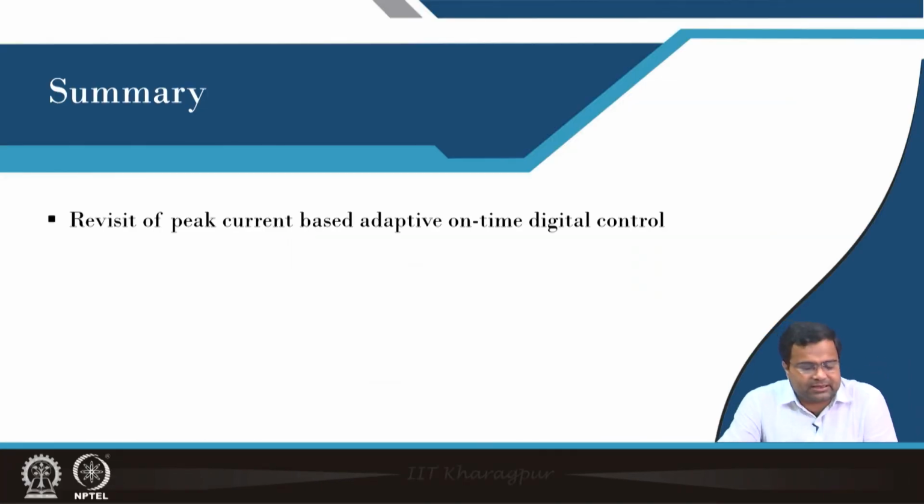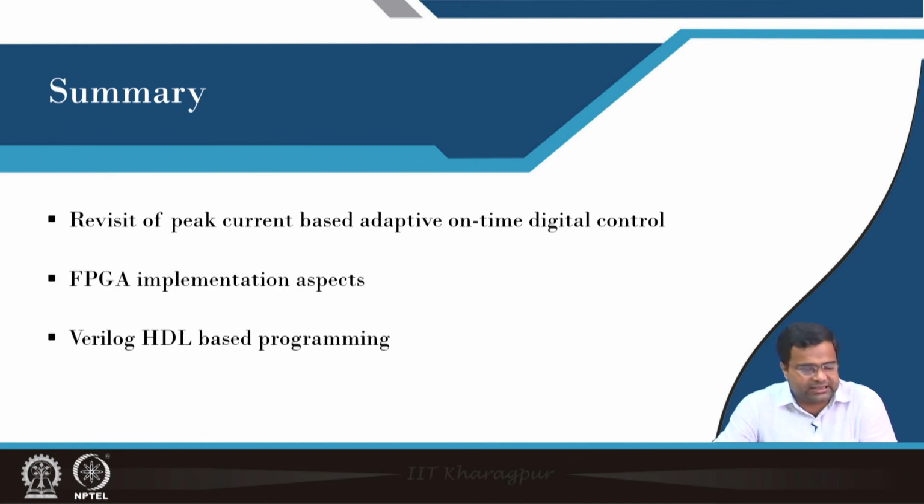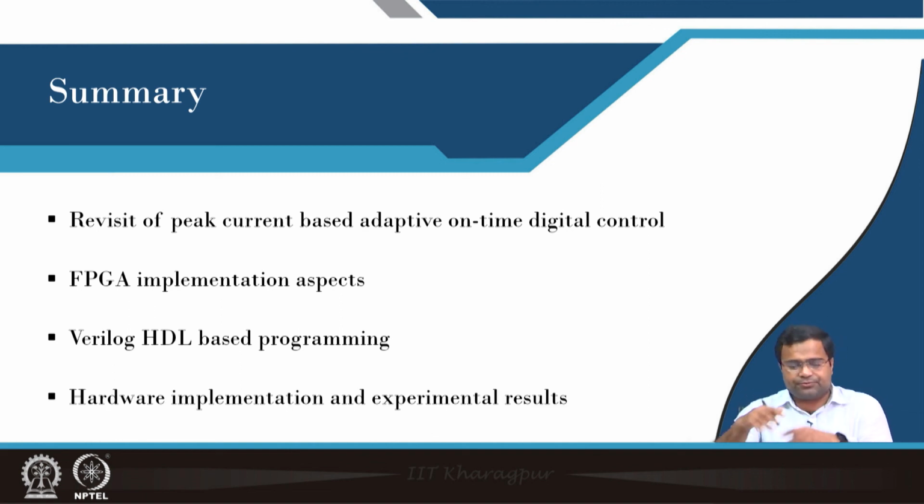So, in summary, we have discussed the peak current based architecture and its FPGA implementation aspects. We have also discussed Verilog HDL programming of this adaptive on time digital control, and we have shown the hardware implementation as well as experimental results.